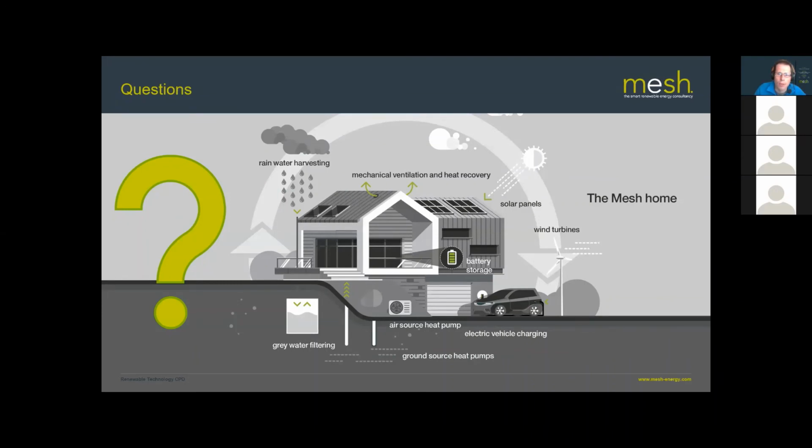Rob, your question about costs, hopefully that has been answered. Is it worth using PVTs, which are combined PV and solar thermal panels, with a ground source heat pump, storing residual heat in the ground in the summer and drawing it back in the winter? I've seen that type of system used. Whether it financially makes sense for most buildings would be debatable, but it's something we'd have to do a bit more work on.